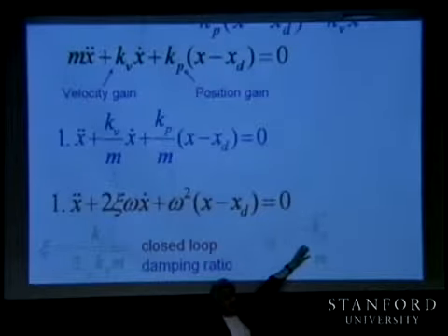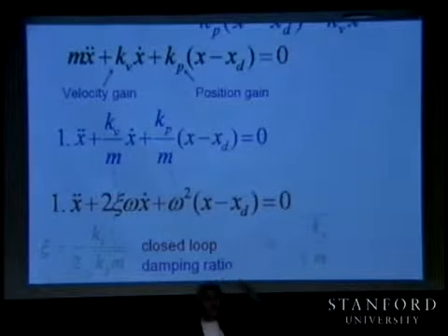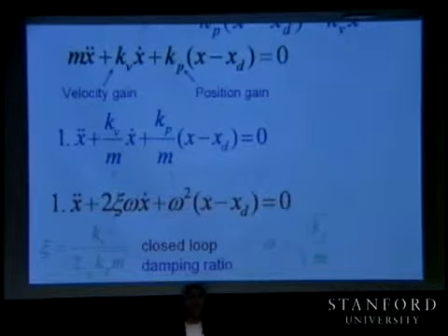However, Kp cannot go too high because Kp is deciding the closed loop frequency. And this closed loop frequency cannot go as high as those unmodeled flexibilities. Actually, we cannot even come close to them. We have to stay away from them. So omega cannot be too high, which means Kp has a limit. But we want to achieve the highest Kp.